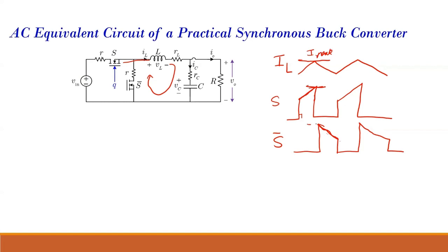If we have this peak reference over here and we are controlling the low side current, it starts at the maximum value, it falls, and this is the waveform which you will see at the low side switch. So in this way, we cannot trigger it at the peak value. Instead, for this we use valley current mode control. When it touches the valley, then we turn off the S bar.